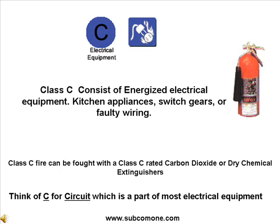Never ever use water on a C-class fire. You could be seriously injured or electrocuted. Always assume, and this is the safest thing, if it can be plugged in, that it is plugged in, and never ever use water on a C-class fire.